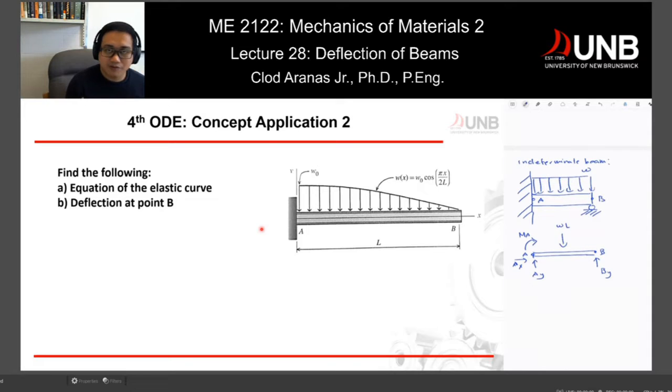Now, if we sum our forces and moments, we are going to get the following. The first thing is X. There's nothing really exciting about X because there's only one force, so you can easily say that A sub X is equal to 0. So that's our first equation.